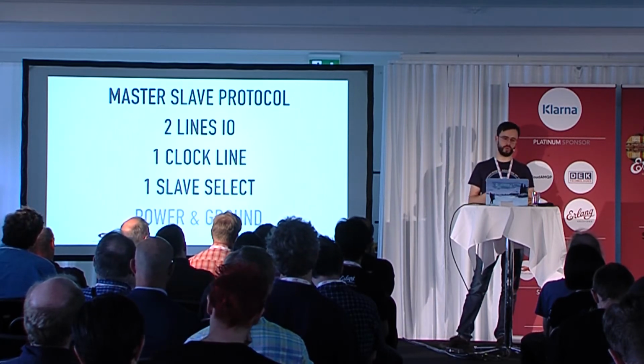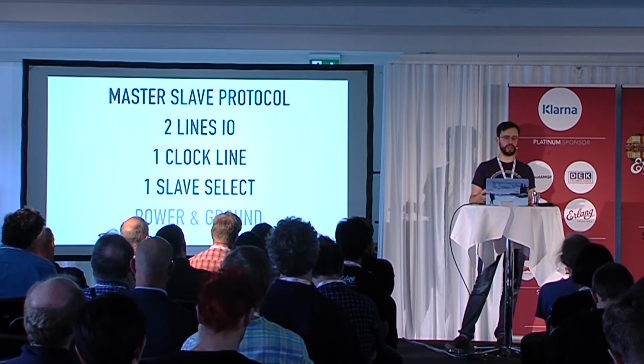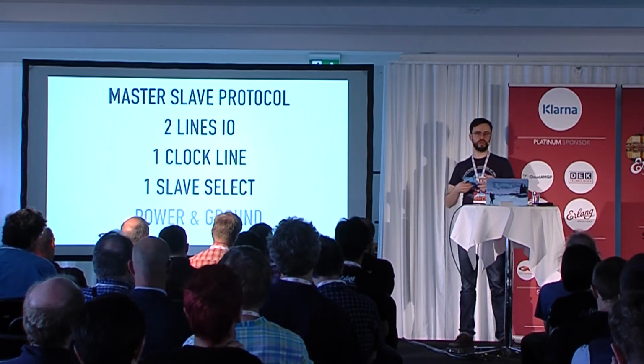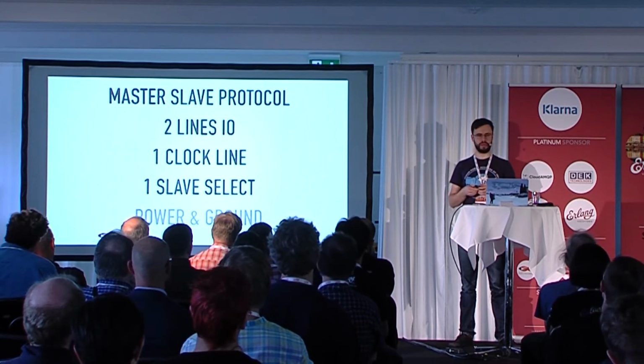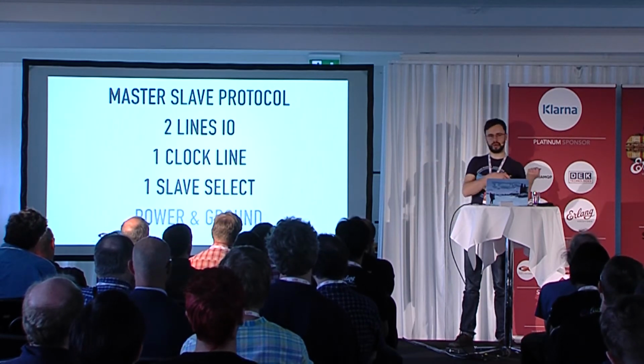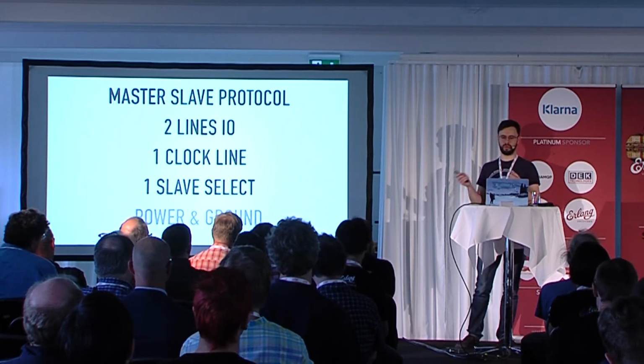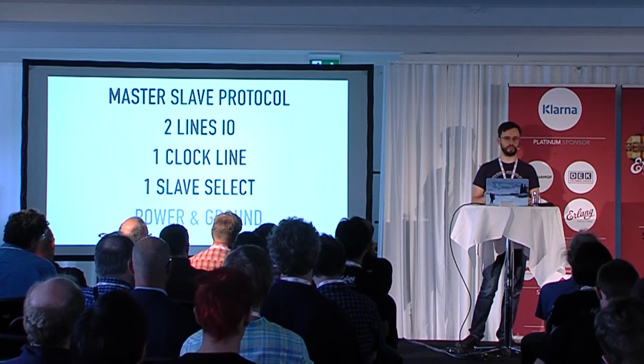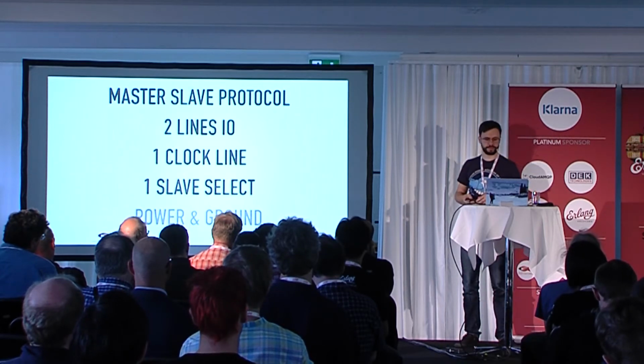On the bigger SPI port we have extra interrupt lines. Some components can listen for events, for example, the accelerometer can detect free fall and then send you an interrupt, which will end up on the GRiSP side, and then we can do stuff with this in Erlang. For example, generate an event or send a message or something like this.